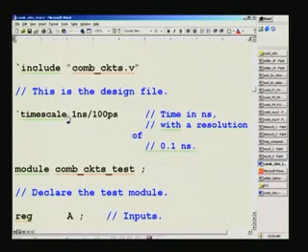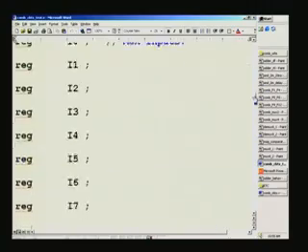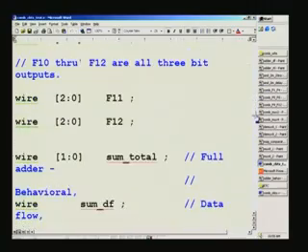We saw that 1 nanosecond is the time base, and you have markings in steps of say 20, the major marking. So 20 into 1 nanosecond is 20 nanosecond. And what about this? This is 0.1 nanosecond. So you can even specify here, instead of 20, say 20.3 or something like that. So you can have it in steps of 0.1. So what will happen if you specify 20.35? What is your guess? What should it be? I will answer that. It will round off to the next higher value. So 20.35 will be rounded off to 20.4, and that is precise.